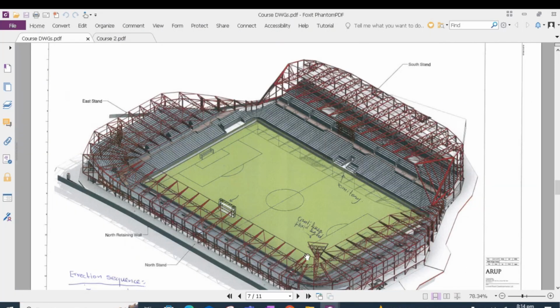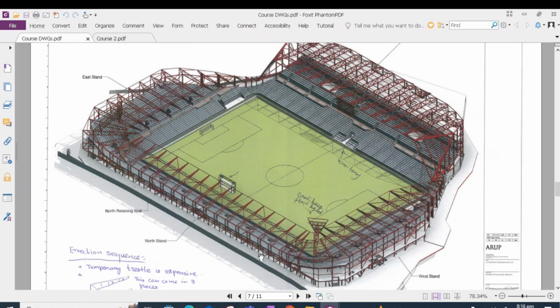This picture shows the cantilever trusses which are placed all around the stadium. And as we saw in the picture previously, there is a straight member joining all the cantilevers together. And also at almost the mid length, there is a steel truss joining all the cantilevers. In the case of Brentford Community Stadium, the load transfer is similar to the single space steel building.